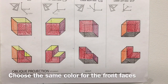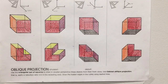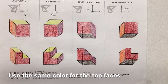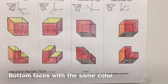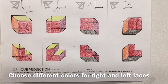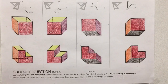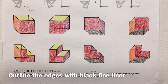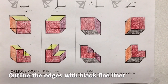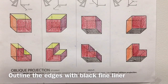I've chosen different colors. For the front face of the object, all of them are red. For the top faces of the objects, we have yellow color. For the bottom, some kind of black color, and then for the right, orange. For the left, purple. All the visible edges are drawn with solid lines using the black fine liner 0.8, and all the hidden edges are drawn with 0.4 millimeters black fine liner using dashed lines.